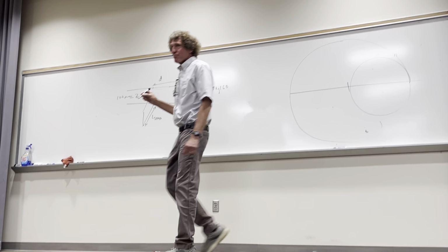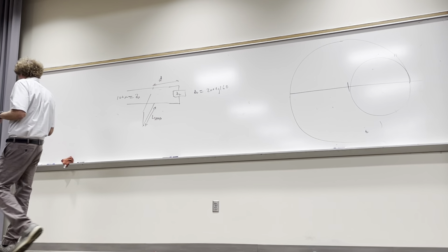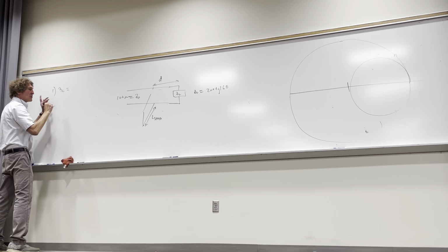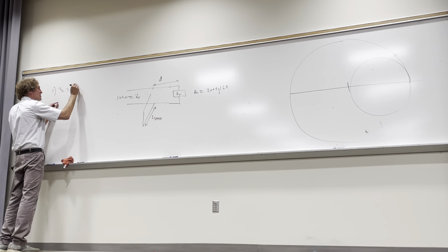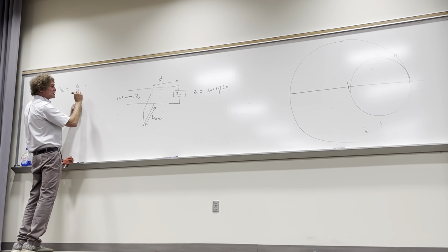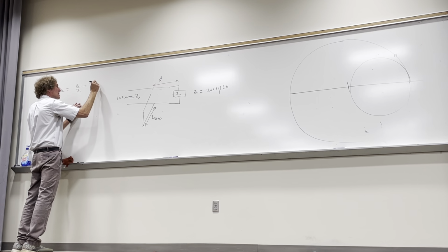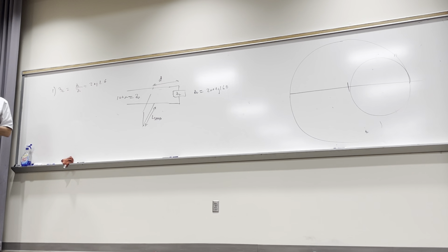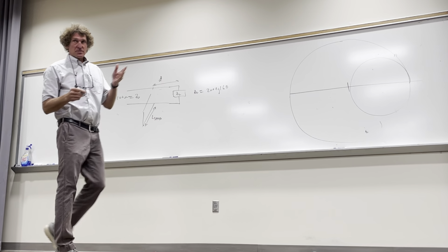Okay, so what's step one? Anybody? Normalize the load. We need ZL, normalized load, which is simply ZL over capital Z naught, and that's going to be 2 plus J 1.6. All right, 2 plus J 1.6. Now, we'll locate that spot just to start us off.